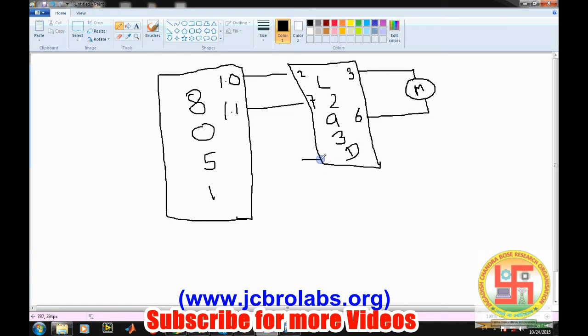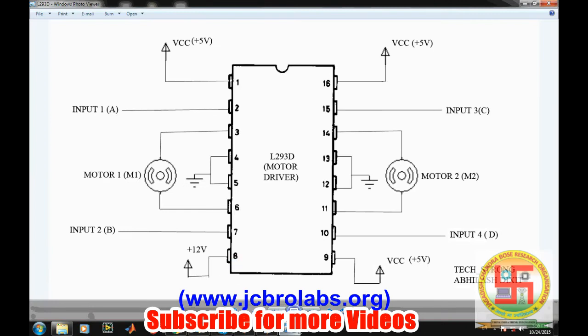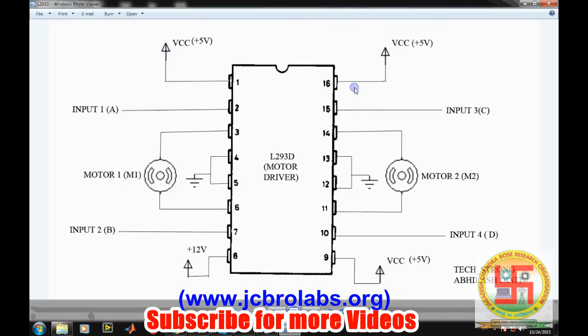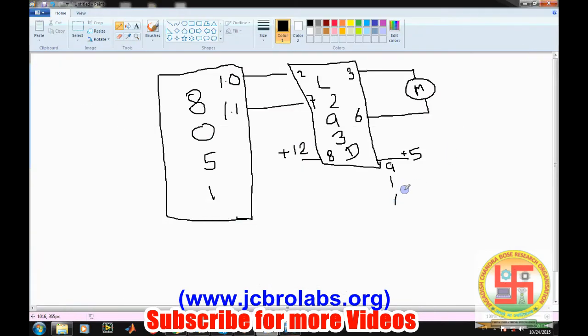We have connected all other supplies: pin number 8 is connected to plus 12 volt, and pin number 9, pin number 1 and pin number 16 have been connected to the plus 5 volt power supply. So this is the complete circuit diagram of connecting the L293D to the 8051 microcontroller. This is the simplest circuit diagram which we can make.